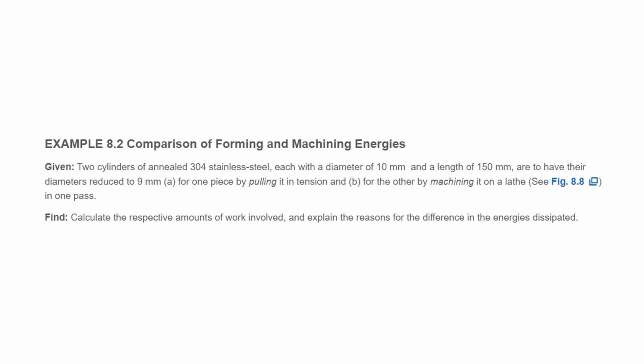So 3.0, 5.2, and we select 4.1 here. This is in the middle, right? This is a range. I just select the middle one. We select 4.1, so this is a unit, and we can just calculate the work for turning, which equals the specific energy, this one 4.1, multiplied by volume. So 4.1 multiplied by volume 2240 gives us 9180 Newton meter.